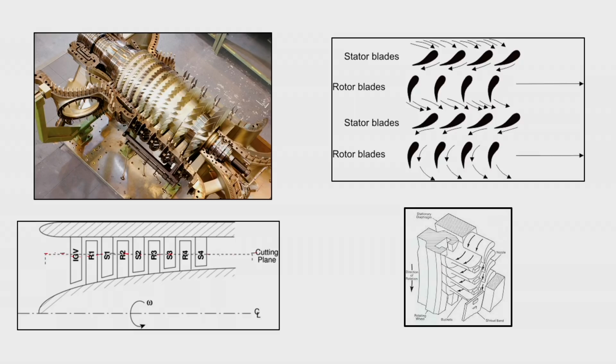In this case we will have a rotor. The rotor blade will pass the flow and impart kinetic energy to the flow, and then it will enter the stator, and the stator will raise the pressure, and then again it will go to the rotor. So the flow passage is rotor, stator, rotor in this fashion in the axial compressor. We can also see how the flow is going in the stator and rotor combination in the axial flow compressor.